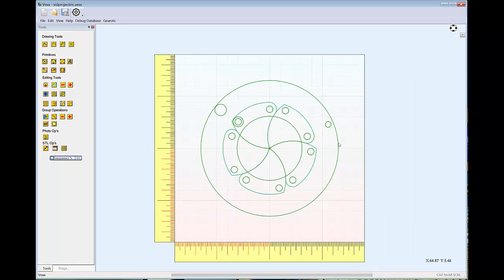Now, in order to connect the ring to the vanes and make them move, we need to figure out what a gear ratio is between the two. There are two ways to do that. One is analytical and the other one is graphical. So let's take a look at the analytical. If we grab a ruler and we measure from the center of the object to our control pin, we can see it's 22.37 degrees up. We'll note that angle. That's the angle that the ring rotates when it goes from closed to open, 22.37.